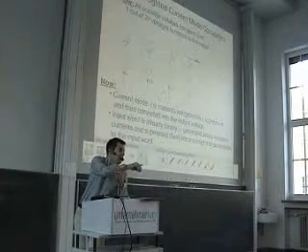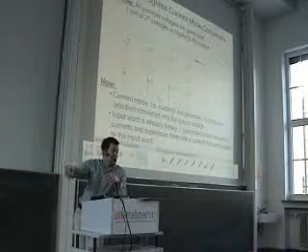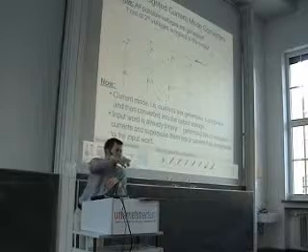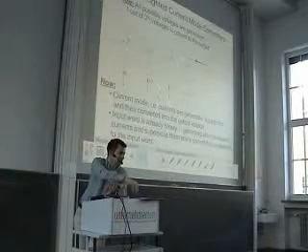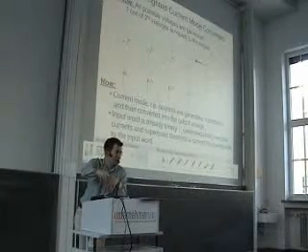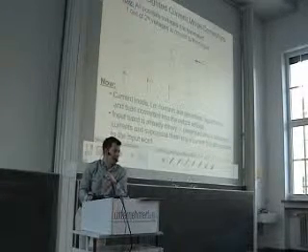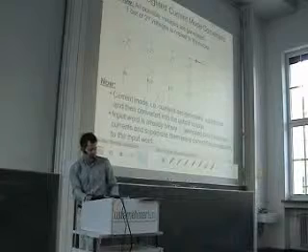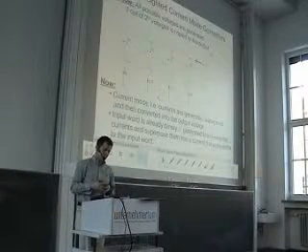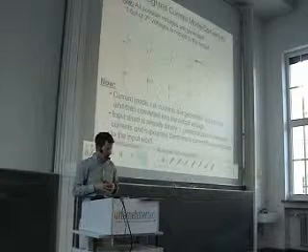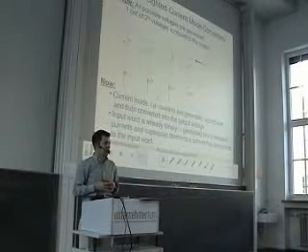Old technique was generate all voltages, select the appropriate voltage. Now we say we generate first currents according to input bits, then we add several currents together, and then we convert this into a voltage. And the second thing that we exploit here is to say, well, the input word is already a binary thing.